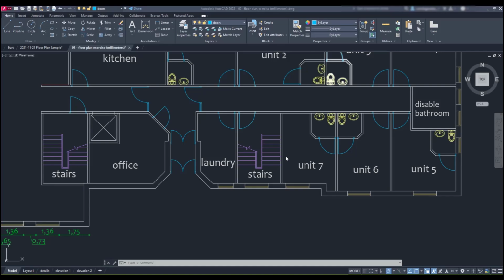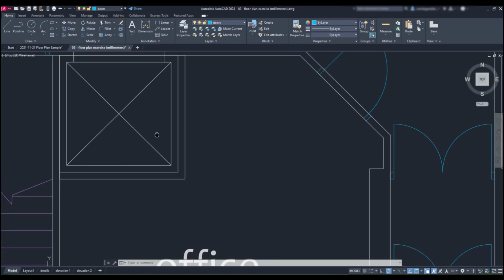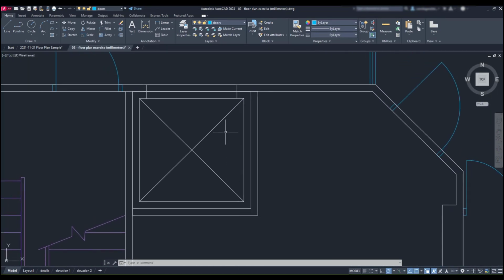Overkill. When we are creating our projects, it's a common thing that some objects overlap others. Like here, when I added this lift to this floor plan. If the project is big and we have lots of duplicated objects, the file can increase its size. But don't worry, because there is a simple tool in AutoCAD to solve this. Overkill. Let's type OV. Press Enter.